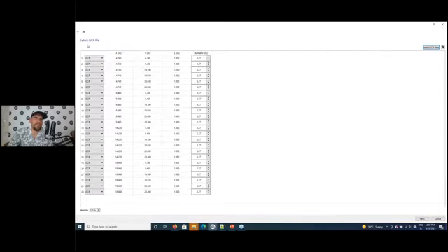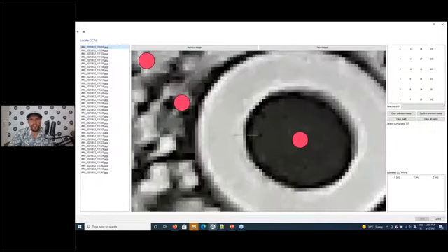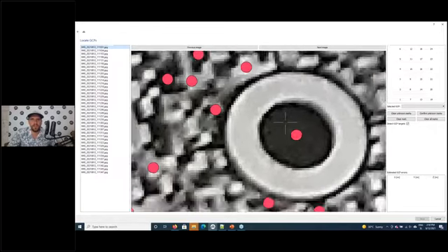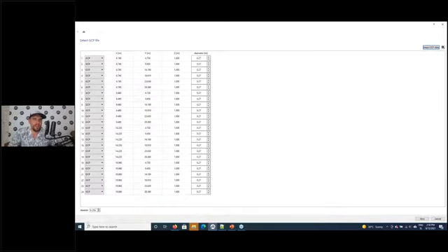Now, important thing before we go into that one is to set up the diameter. So in this phase, you will have to go in here again, take the measuring tape and measure the diameter of this black dot. So if you use my calibration field A4 version, this value should probably print out to about 3.5 millimeters. So I'll go here and I will set this one to 0.35. Go next.